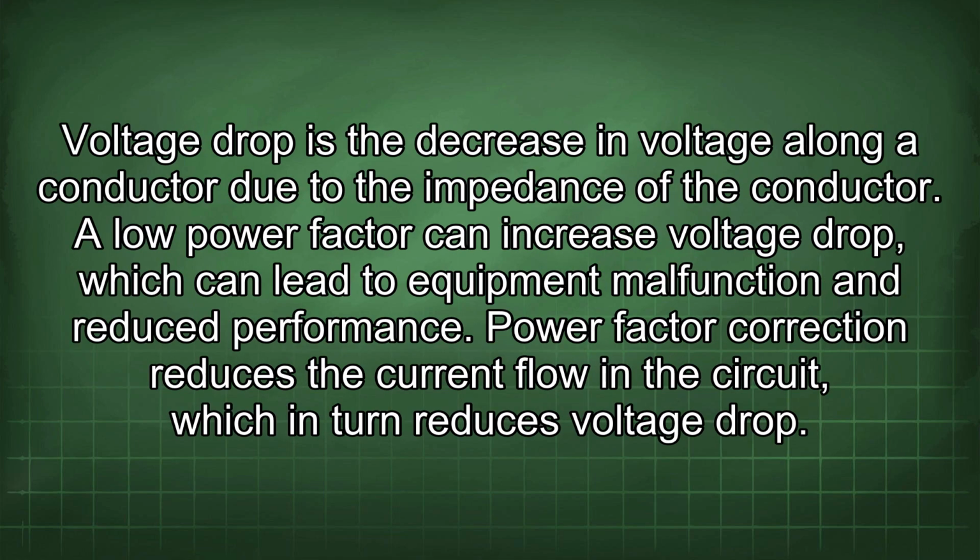Voltage drop is the decrease in voltage along a conductor due to the impedance of the conductor. A low power factor can increase voltage drop, which can lead to equipment malfunction and reduce performance. Power factor correction reduces the current flow in the circuit, which in turn reduces voltage drop.